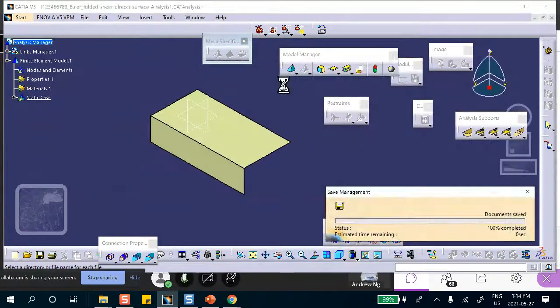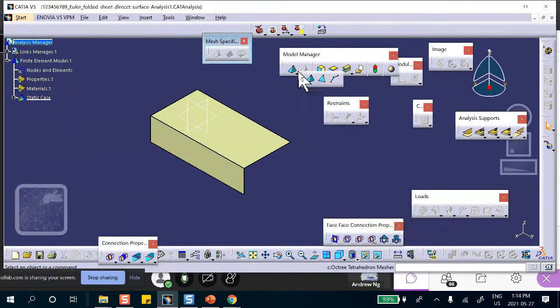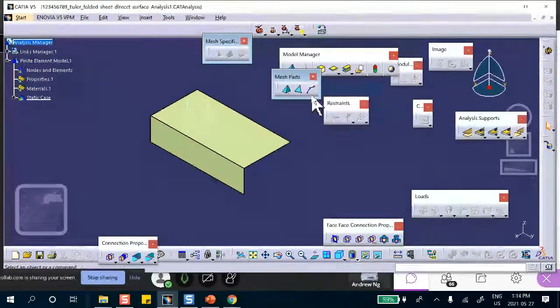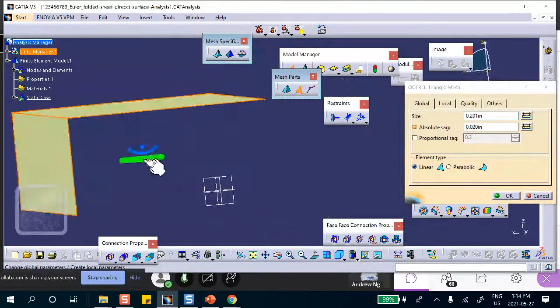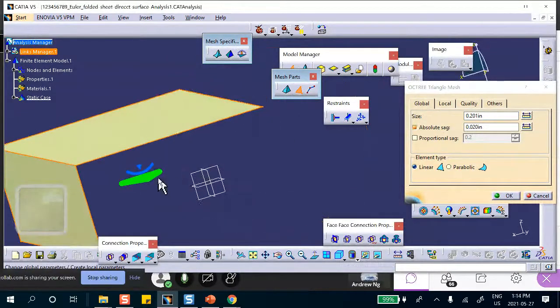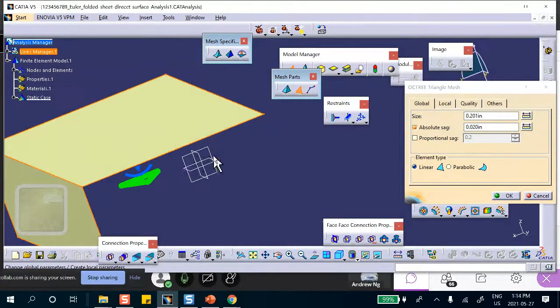Now, our job is to mesh it. Mesh it with shell elements. You remember these: solid elements, beam elements, shell elements. That goes on surfaces. Look, there's no three-dimensionality to this. It goes on a surface, basically. You click on it, you select the surface, so it's going to try to put elements of that size for you. Notice that there is no thickness here. You can see that on these faces.